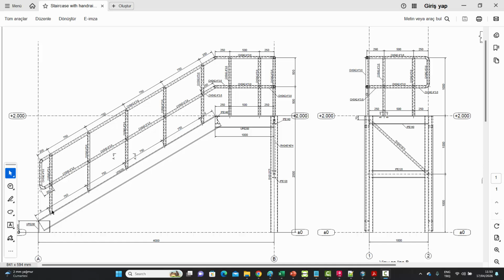Now let's try to enter the posts of the handrails, and these posts are 750 millimeters apart along the stringer, and then we have an X at the start and at the end, and there are 4 of these 750, so there's 5 posts basically, 1, 2, 3, 4, 5, and the distance between them is 750. So let's see what we can do about that.